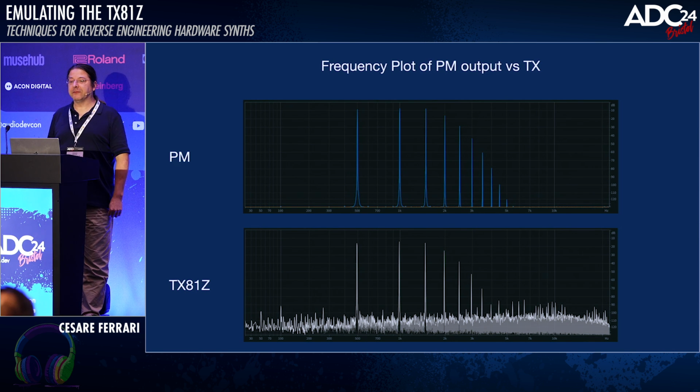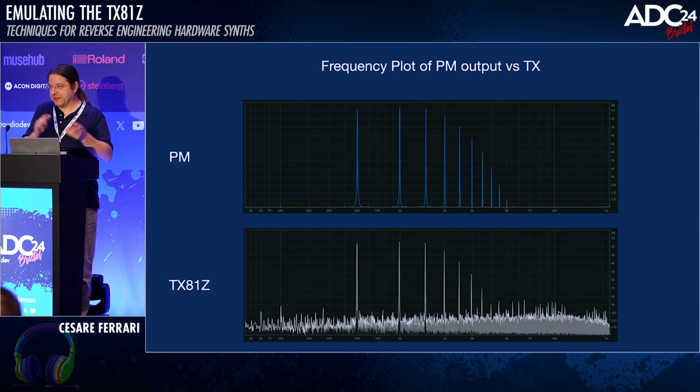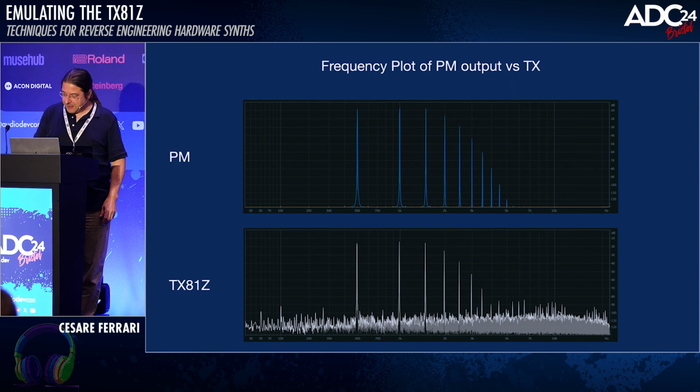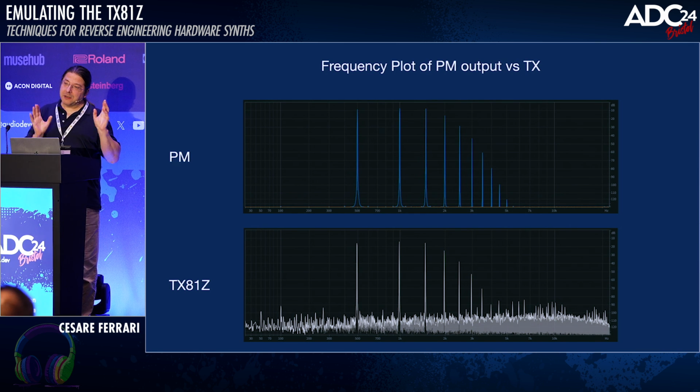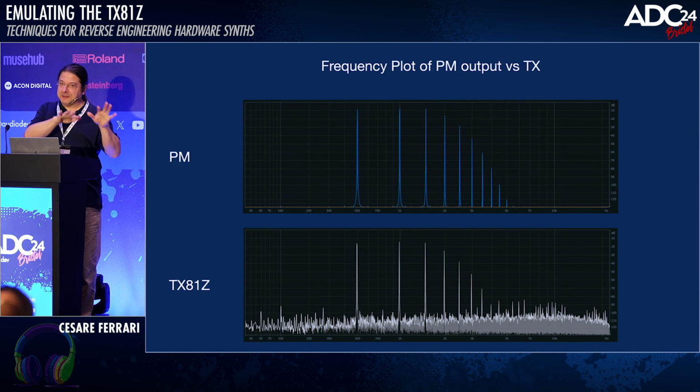DACs in 1987 were fascinating things. They were expensive, and they were quite limited in ways that we just take for granted, when everything is now 24-bit and can go to ridiculous speeds. The Yamaha instrument uses a 16-bit DAC, which is not really 16-bit. It's got a 16-bit dynamic range, but it's actually only got 10 bits of resolution. So it shifts the 10 bits up and down depending on the current value. It's very clever.